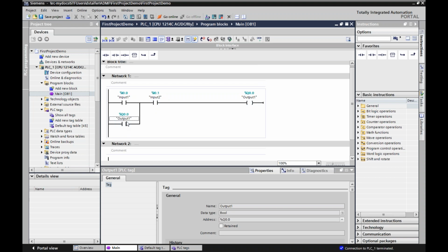Or if this is on already and this is on, keep this on. So when this isn't running, this will be false and this will be false. But when I hit this online, this turns true, this stays true because it's a normally closed stop switch. At least that's what we're doing in our simulation. This turns on, which then makes this true, so then I can turn this off. So let's demonstrate this.